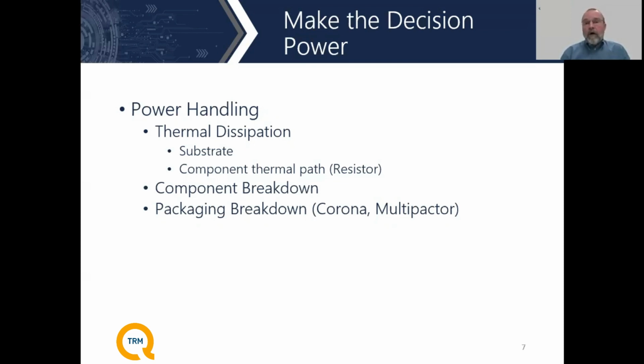Very often we see engineers trying to be very conservative as far as what they're rating the power of these individual parts at, and really it ends up driving the design into something that is adding a tremendous amount of cost. And when you understand how the part's being used, you have to scratch your head and say, well, gee, why did the engineers specify the power levels that high? Especially when it's operating at 1/10 that value.